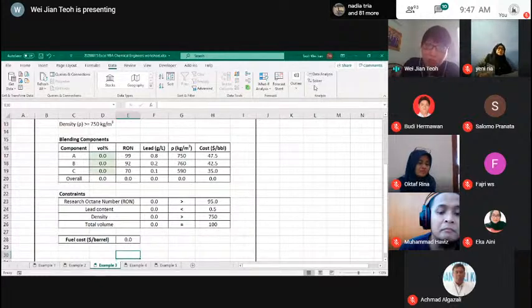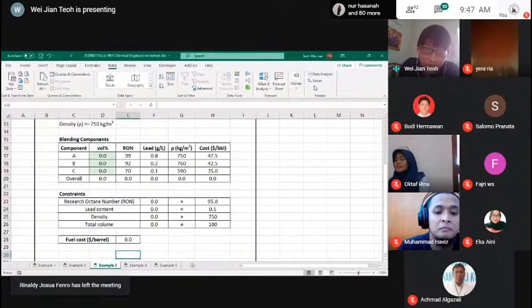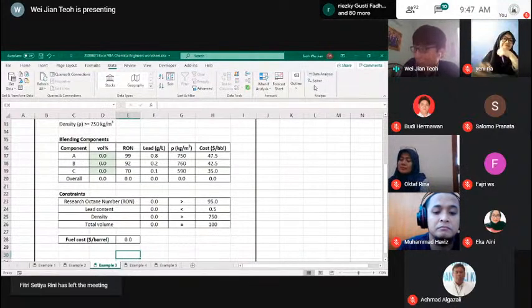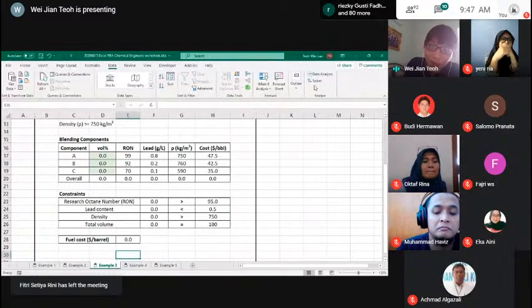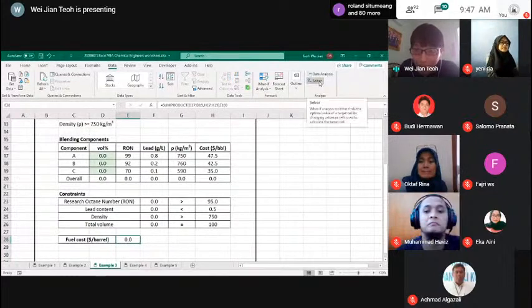So you might have a different version of Excel, then some of the steps will be slightly different, but they'll be generally in the same place. If you have some trouble, please type in the chat box if you cannot find where Solver is. Okay. So I'm going to use Solver now. I'm assuming that you guys have Solver. So I'm going to click on Solver.